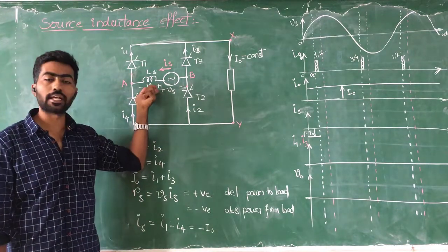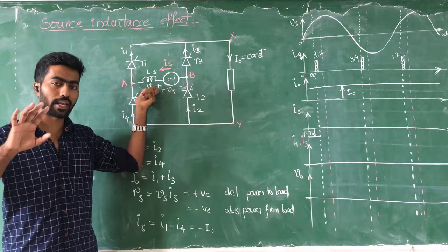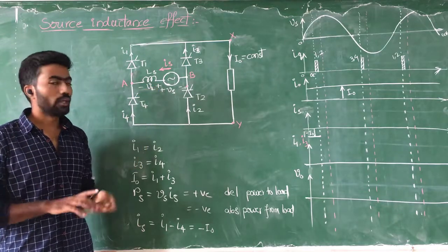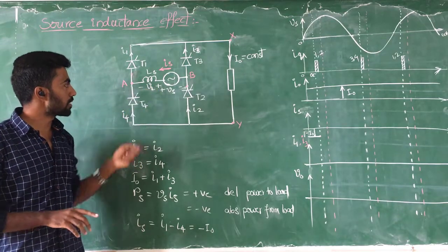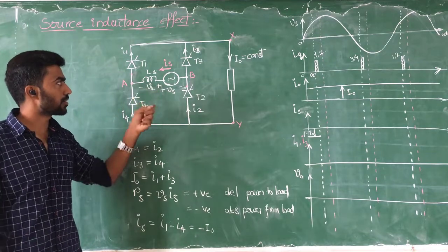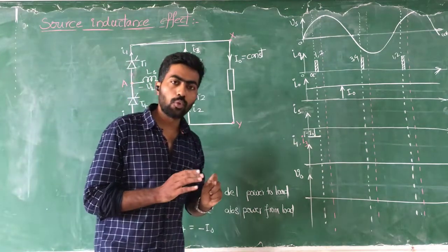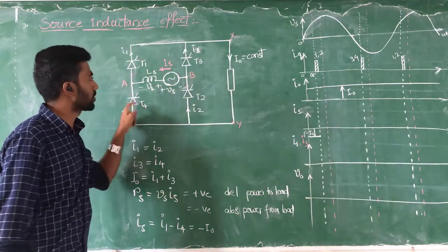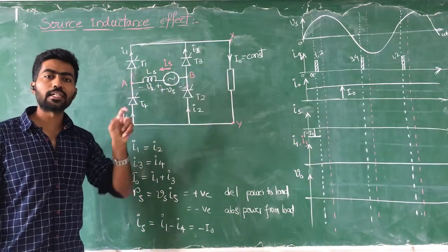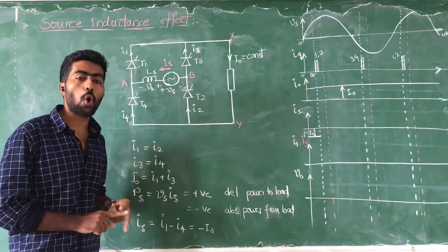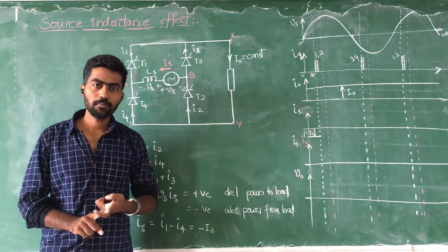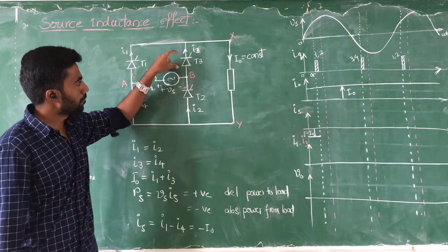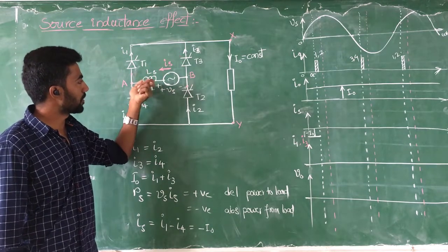Because of the source inductance, all four devices conduct for a certain duration. That duration is the overlap period.